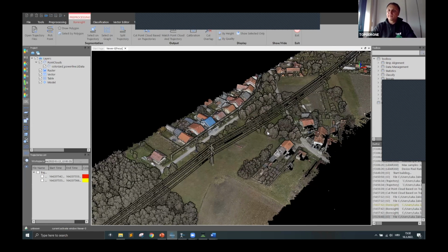We're having another question from Malik. What is the way we control the final accuracy for the LiDAR survey? Using GCP or something like that, or ICP? So from our experience, the best way to have good accuracy is to have your GNSS base station really close to the area that you're surveying, and also to have calibrated your LiDAR. But I think, Maxim, you can maybe suggest something else to improve accuracy.